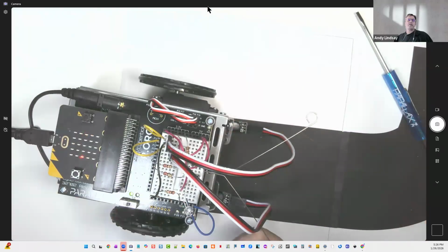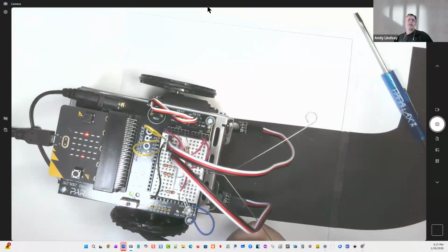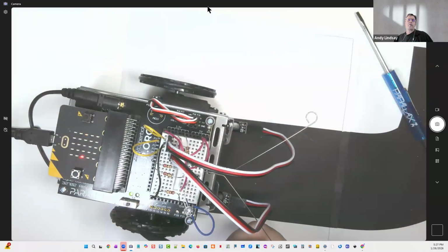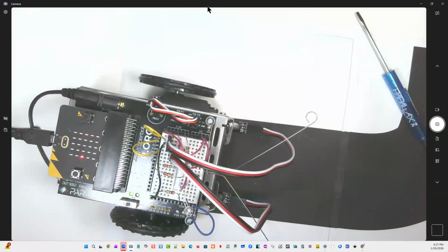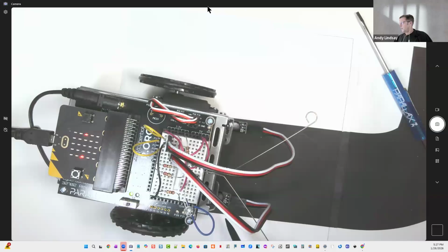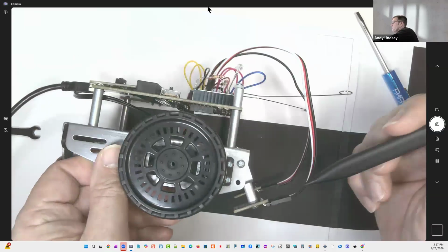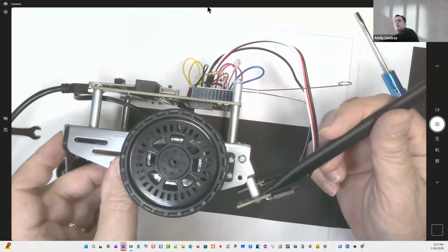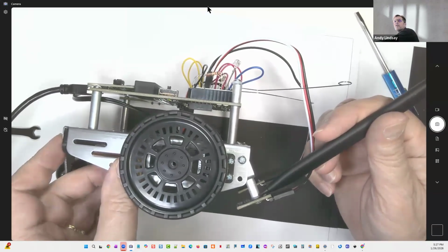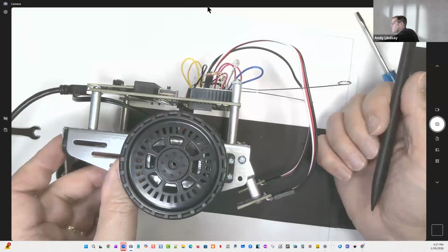I guess another thing you could do is temporarily remove the little rubber tire. That'll drop it a little bit too. The nylon washer that goes up against the QTI, does that insulate for continuity, or is it there as a spacer? It's just there as a spacer. So for example, if you needed the QTI to be riding higher, you could remove that nylon washer.